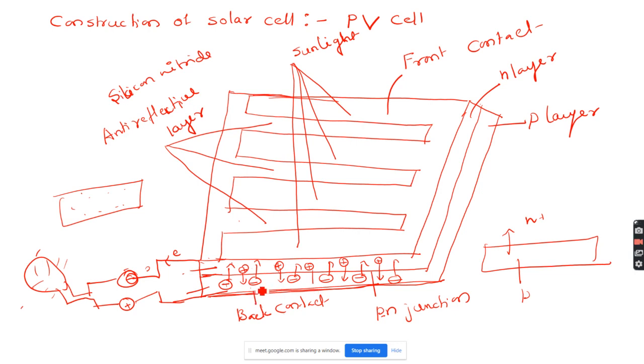The electrons usually drift and are collected at the N-type semiconductor, at the border. All negative charges are collected in the N-type semiconductor, and holes drift towards the P-type semiconductor. As a result, an electrical double layer is developed. When these ends are electrically charged, one becomes completely negative and this layer completely positive. So these ends are electrically charged because of the separation of charges.